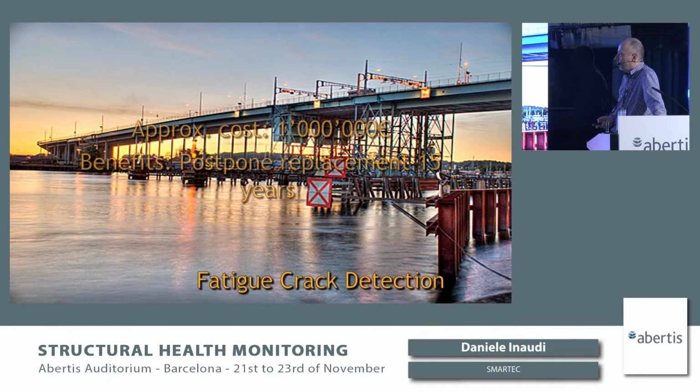That's quite a challenging question because you have no idea where the cracks might appear along the 1 kilometer long bridge. So what we did was to install a distributed fiber optic monitoring system, and that was very expensive. It's about a €1 million project. But it allowed the postponement of the replacement of the bridge for about 15 years. So that system was installed almost 10 years ago, still in service. And we're going to use it for 4 more years until the new bridge comes into service.